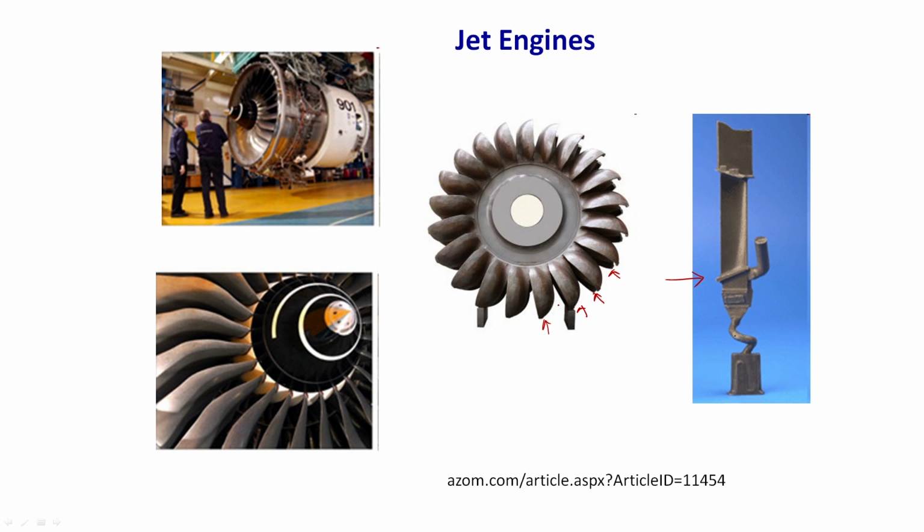There are many other elements present. There are 13 elements present in this kind of alloy, and that is one of the major discoveries of material science, which has given the best technology possible in this world. These blades are actually single crystals, by the way. They are single grain, each blade is one grain, and they can be 1 meter long.